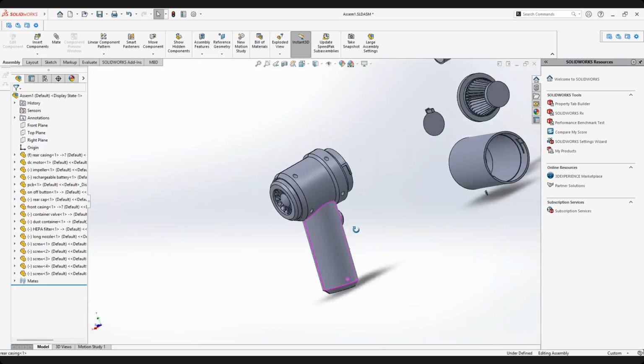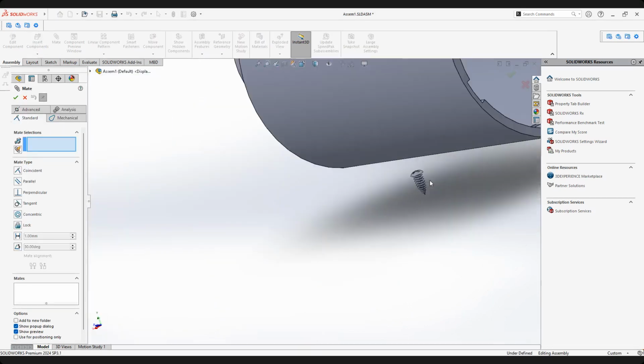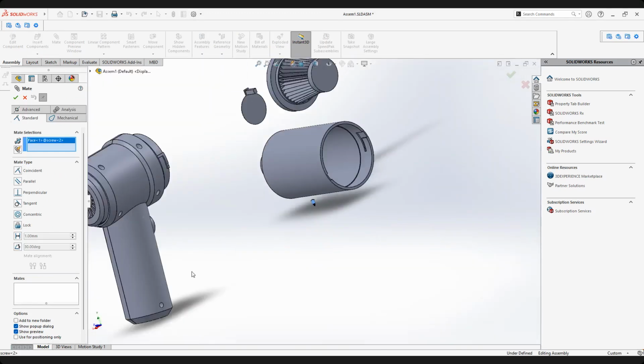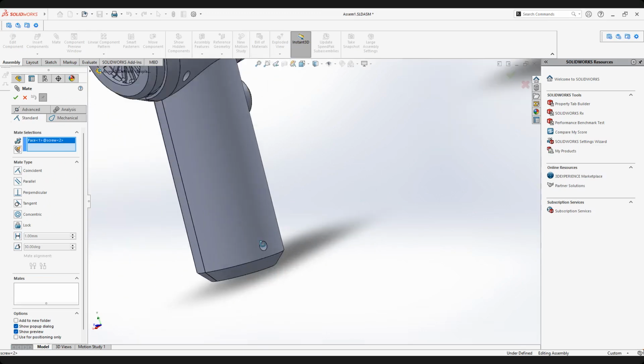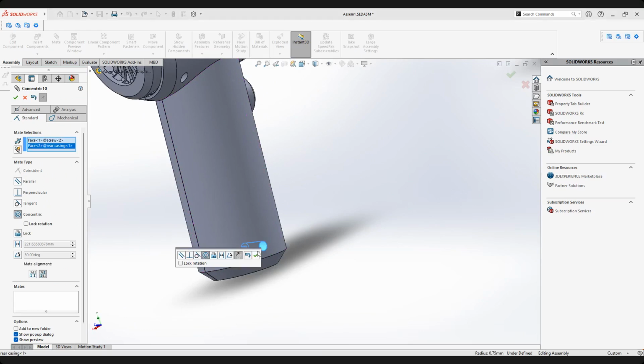Okay, I have one more screw to go, right? Okay, one more screw. Screw that do not mirror, guys, in assembly. So your screw thread will be mirrored. That's wrong. In assembly, screw do not mirror. Take note.